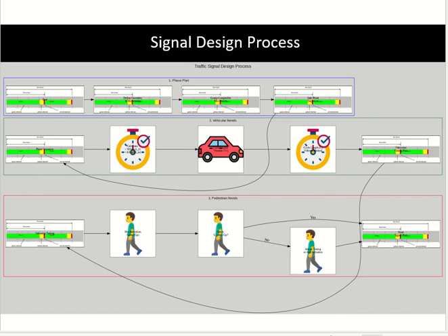Okay. So first of all, you calculate how much time the pedestrian needs. Then you check, because you already calculated the green time, if this time is enough for the pedestrian. The green should be more than what the pedestrian needs. If it is not, then you will do the adjustment. If it is equal or more, just leave it and move on. But you have to do it for each phase.